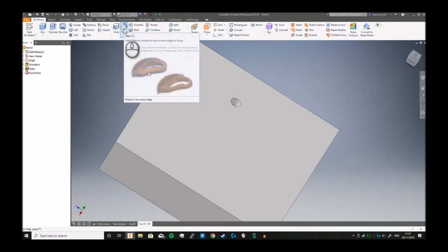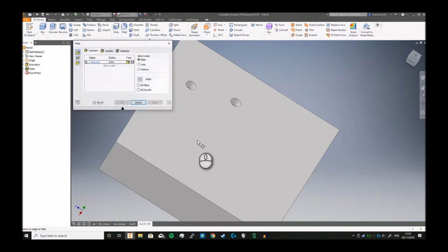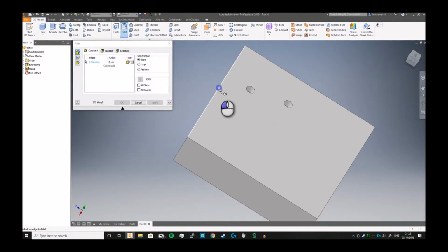The next thing is onto fillets. Fillets just round off edges and more transitions between two faces. You literally just select the edge and it applies a fillet. There are 3 types: Tangent, also known as G1, smooth, G2, and inverted. Well, they can come to a separate video if people want to know, but it's just how smooth it is transitioned. You can look at zebra analysis and to the naked eye you can barely tell,